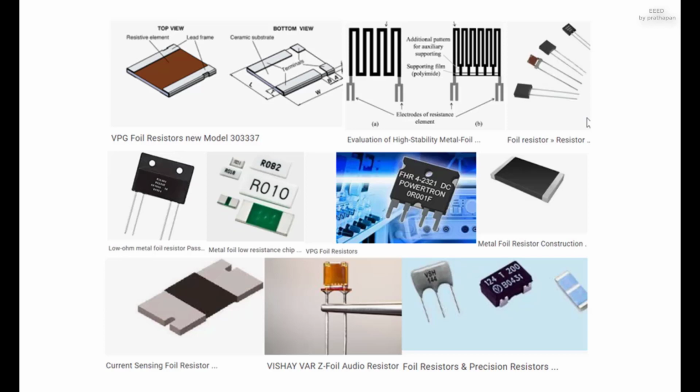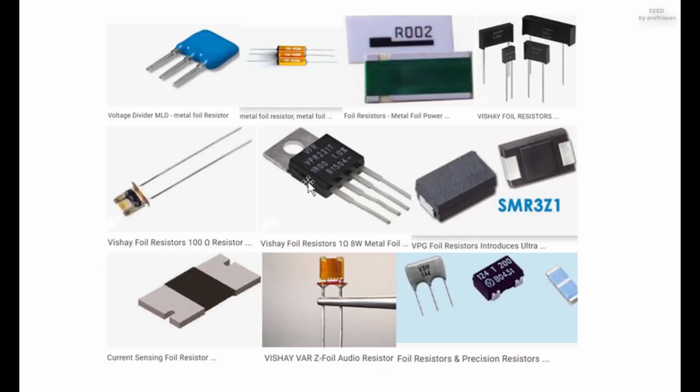The thermal stability of this type of resistor also has to do with the opposing effects of the metal's electrical resistance increasing with temperature, and being reduced by thermal expansion, leading to an increase in thickness of the foil, whose other dimensions are constrained by a ceramic substrate.